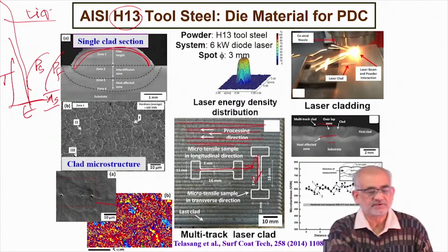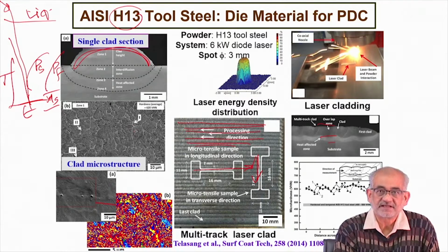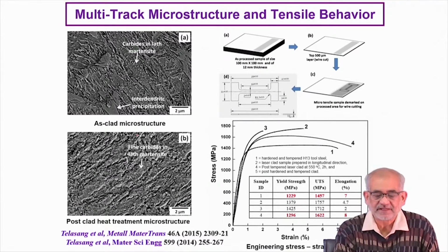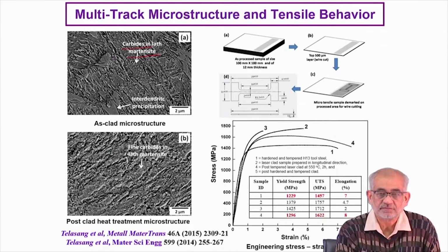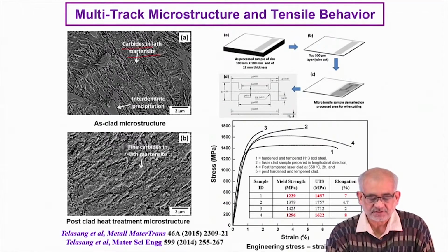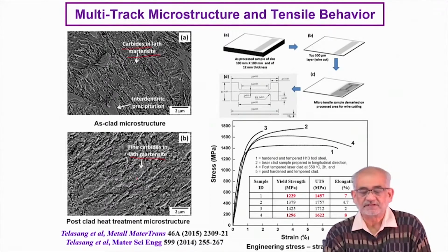So the cooling all the way from the liquid state to room temperature in this particular case allowed formation of not only the solid but solid in the form of shear transformation product or martensite. And by the by, along with martensite, there were also plenty of carbides formed during this cooling process. So very fine carbides in between the laths, martensitic laths, created a very good mechanical property.